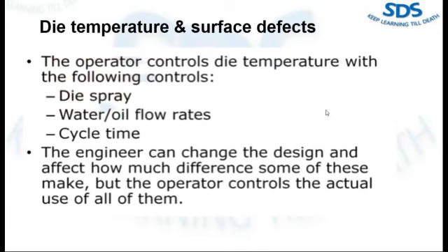We should make all operators aware: you are the prime responsible person on the machine for maintaining this die temperature, and the die temperature is important to resolve this surface defect. So the operator should know he can maintain or control this die temperature.